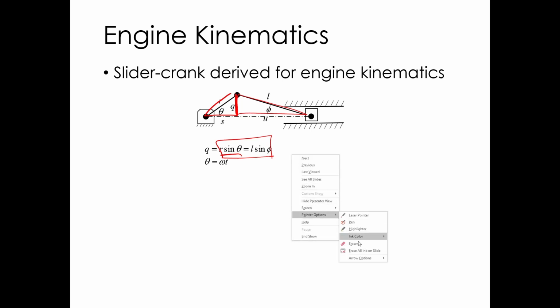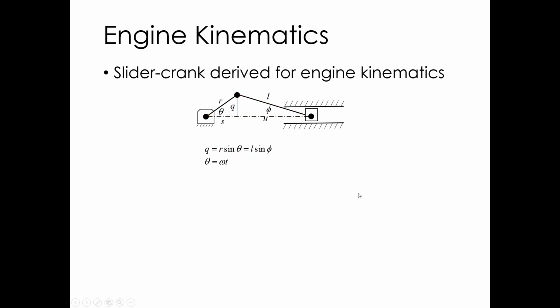All right, so we're going to assume constant engine speed, which honestly is not a bad assumption in engines because engines usually spin at high speed, and that speed doesn't change very quickly. So most of the effects are from an engine running at speed, not the speed changing. There's an effect on the forces and accelerations from the angular acceleration of the crank, but it's going to be relatively small compared to just the forces required to sling the piston and connecting rod and crank around at higher constant engine speeds, near the max speed of the engine. So not a terrible assumption here.